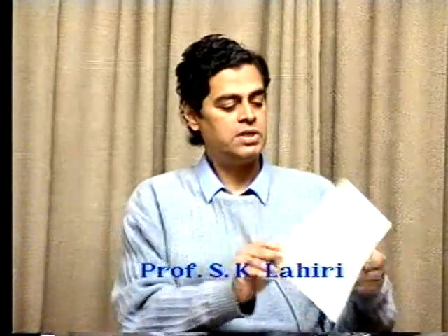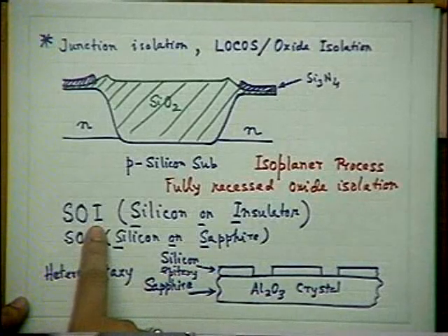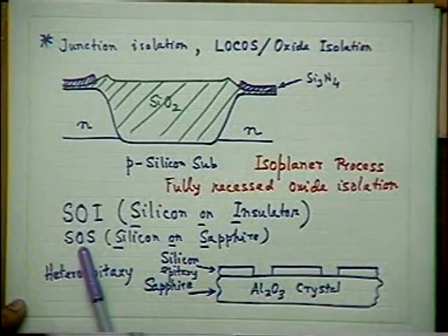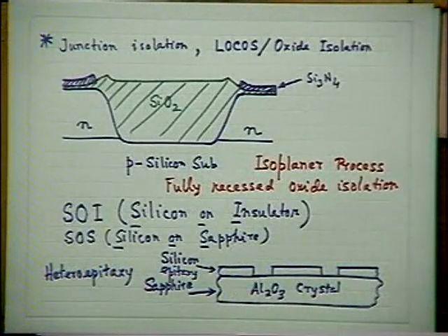And therefore, people are saying that this expensive technology perhaps will be confined to future space applications and very specialized military applications. But you know that there have been some intermediate solutions. And that is why the general name SOI was given, this is a general name, okay? And this is the extreme solution. SOS is the extreme. You just start with an insulating substrate on which you grow a silicon film.